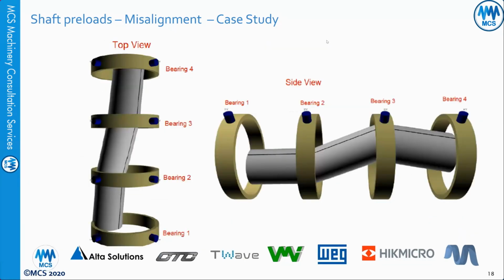One of the good things from the Emerson system, which is the MHM software, is a good feature that lets you make a 3D animated shaft. From the time waveform, you can animate the shaft if you have the measurement at the 4 bearings. If you look, this is bearing 1, which is the non-drive end of the turbine, and this is the drive end of the generator and non-drive end.